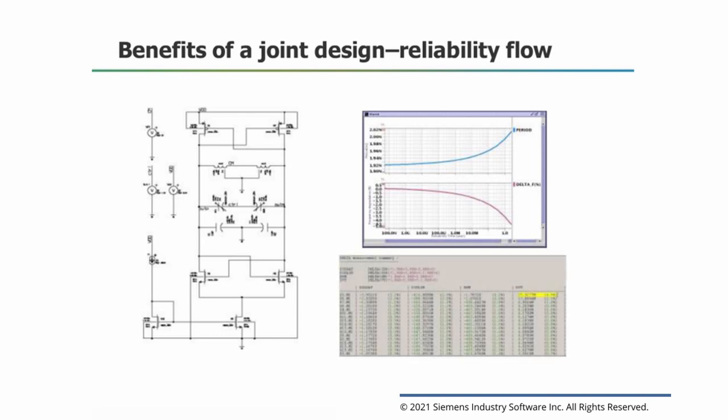The next thing a designer needs to know is which device is primarily responsible for the degradation of the observed metric. The simulator reports the devices that have their threshold voltage degraded the most severely, sorted by decreasing delta VTH. This allows to immediately identify the sensitive part of the circuit and make the design robust against aging.